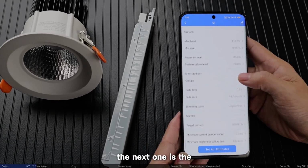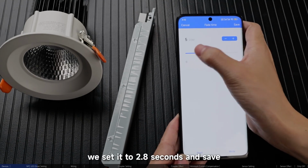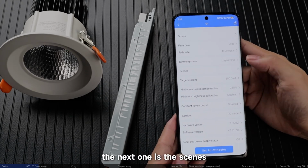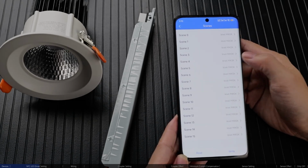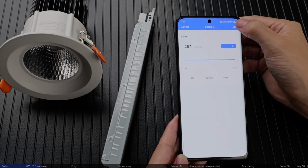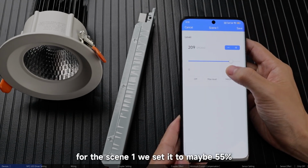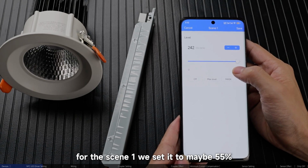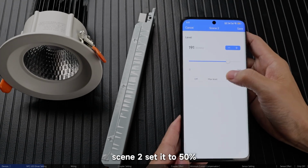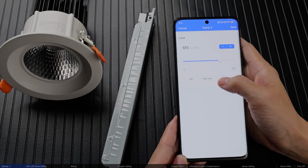And next one is the fade time. We set it to 2.8 seconds and save. And next one is the scene. Maybe for the scene 0 set it to max level. Okay, save. For the scene 1 we set it to maybe 55%. Scene 2 set it to 50%. And the scene 3 we set it to 25%.